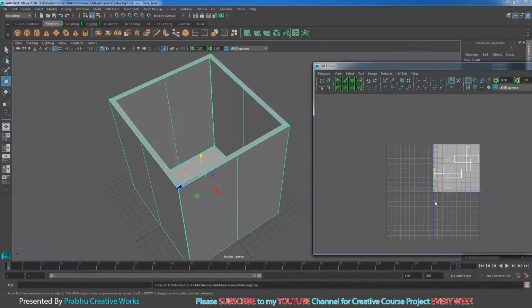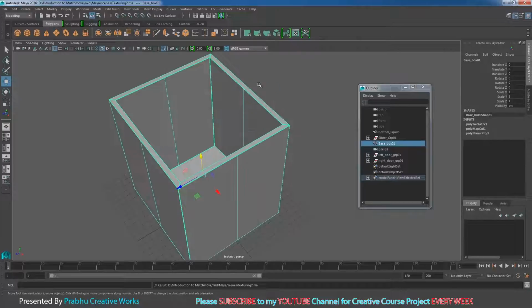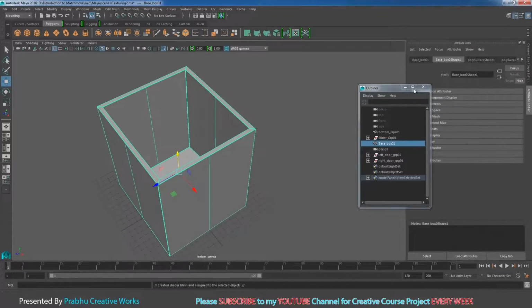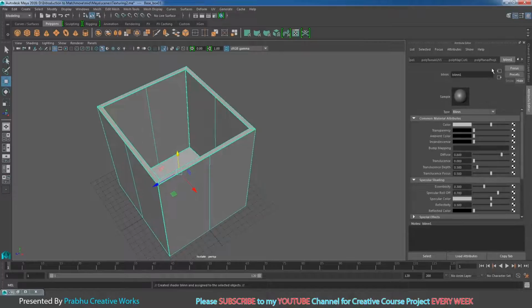I want to go to Maya. So I will close my UV editor. Right click on this object and choose object mode. Right click and choose assign new material and choose blend. So I want to rename this blend. Go over to the blend here and rename this blend as box underscore blend 01.